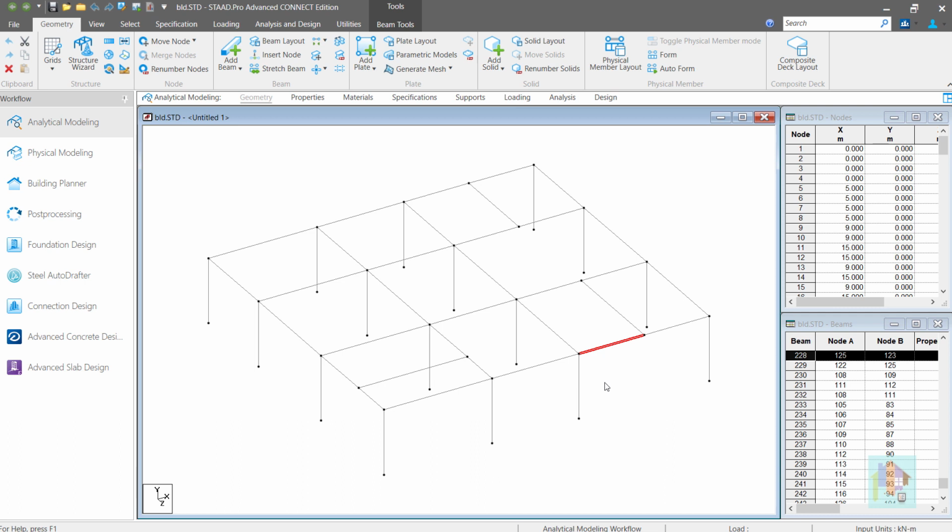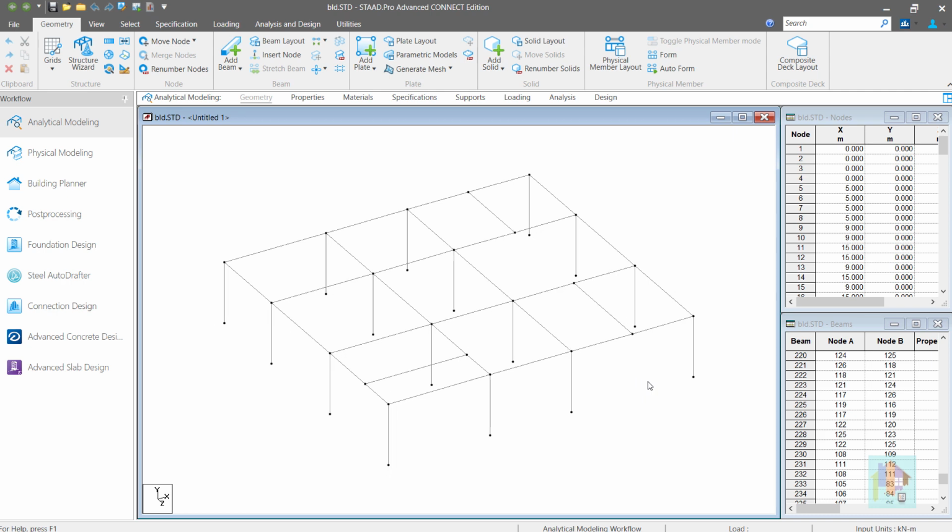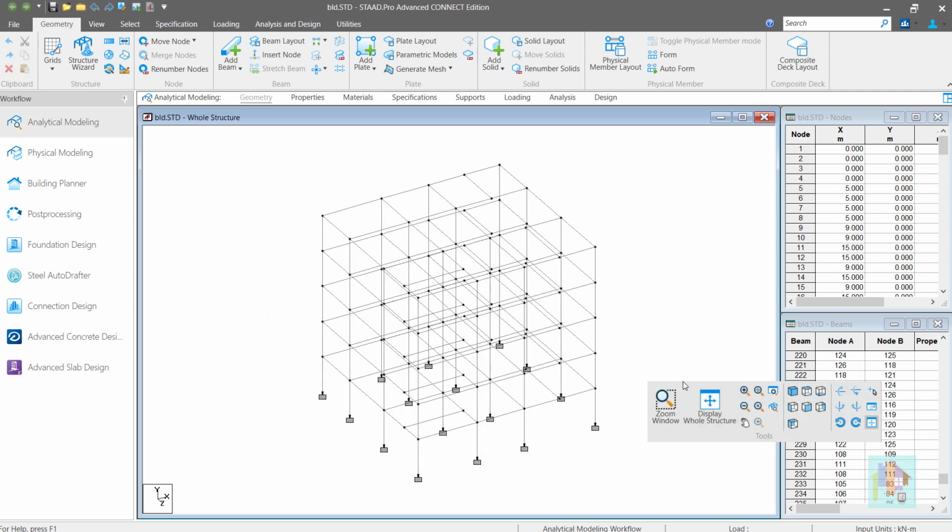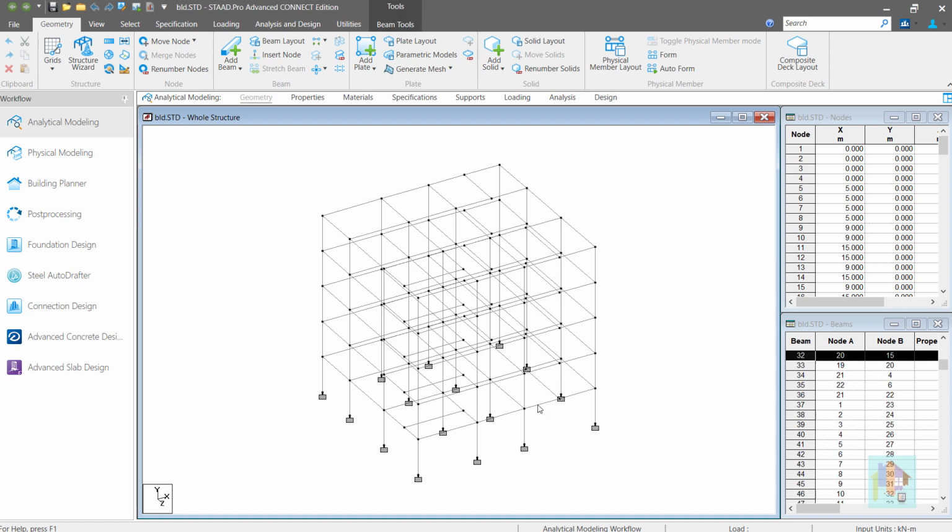Now, due to these internal joints, primary members divide into several parts, and this causes some problems during the design phase. For an analytical model, the program doesn't have any idea about the full member, and hence for concrete design, different reinforcement is provided in different spans. And for steel design optimization, different sections are selected for different segments of the member. This is a non-realistic condition, right?